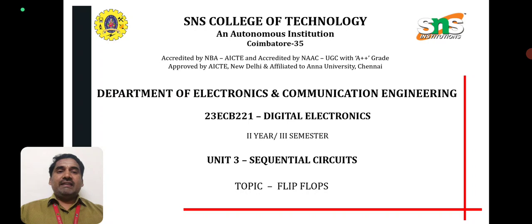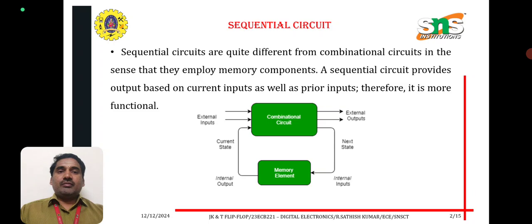Now let us see another video lecture series on sequential circuit flip-flops, JK and T flip-flop. First, what is meant by sequential circuit? Sequential circuits are quite different from combinational circuits in the sense that they employ memory elements. A sequential circuit provides the output based on current inputs as well as prior inputs. Therefore, it is more functional.